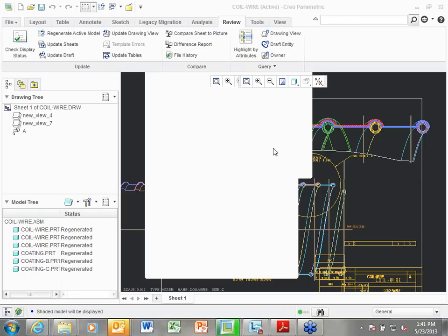Do you want a square or do you want a round? I don't have to even reprogram anything. You can just add that right into the input. But only if it's always a square or always a round. Or maybe I want to change that diameter, and then you'd have to add that relation. The key is the relation has to have that, not the program. The program will actually see it. That make sense?